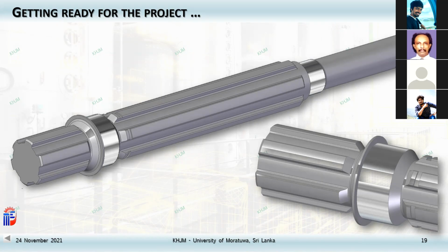And maybe you can go back and then check for the strength, the bending, for example. And then there are many other things coming up which will increase the stress concentrations. Maybe you have not calculated those things. You have not accommodated for this because you were thinking of one straight shaft. So you have to go back and change the calculations. When you do the calculation, you can see sometimes somewhere it's going to fail.